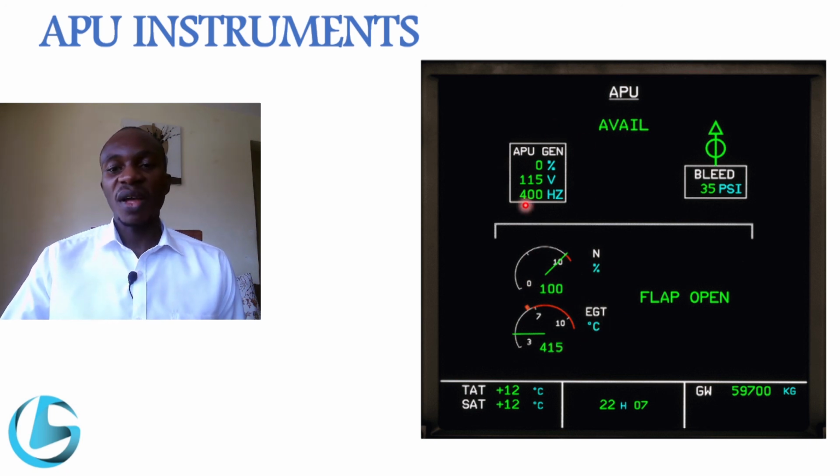We also have the status of the APU generator, the voltage being produced by the generator and the frequency of the voltage being produced. We also have the bleed air being produced by the APU. See if the bleed valve is closed or open. Like in this particular case, the bleed valve is open. And we see the pressure of the bleed being supplied by the APU.